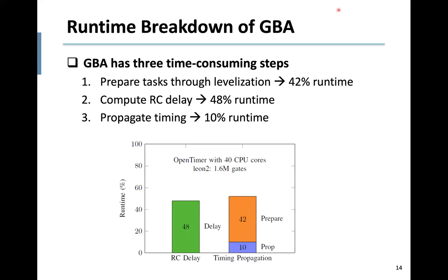Yes. Can I ask you a question? So what do you use for the cell delay models? Are you using like a current source model or just a voltage-based model? Right now we use a nonlinear delay model, and I will talk about that later. Yes, that will be covered in the later slides.